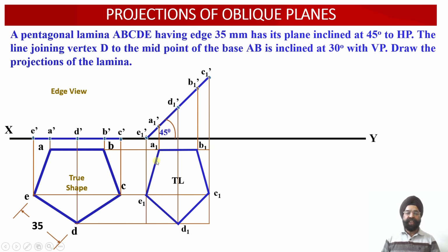That is, this plan projection view we are required to transfer at an angle of 30 degree to the vertical plane in such a way that, onto this orientation projection line which we have drawn at an angle of 30 degree, the line which joins vertex D1 with the midpoint of the edge A1B1 should be lying over there. So how can that be done?